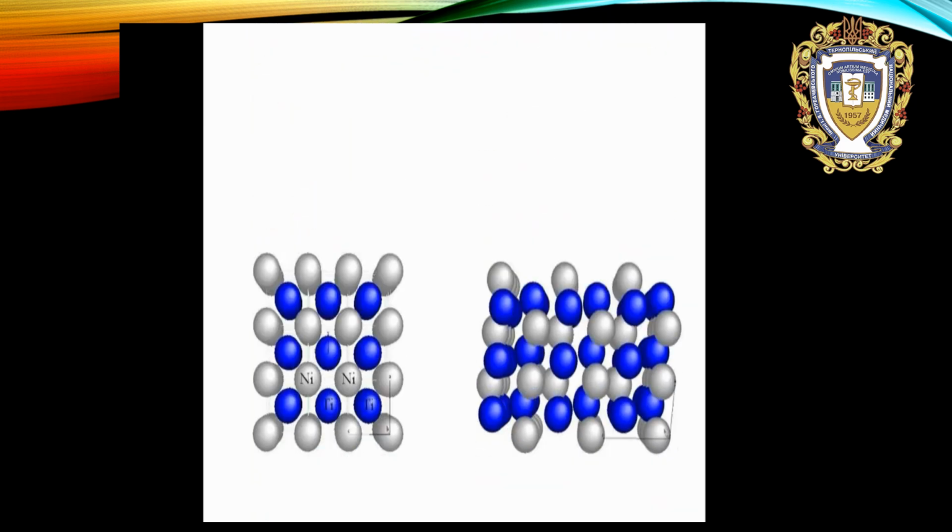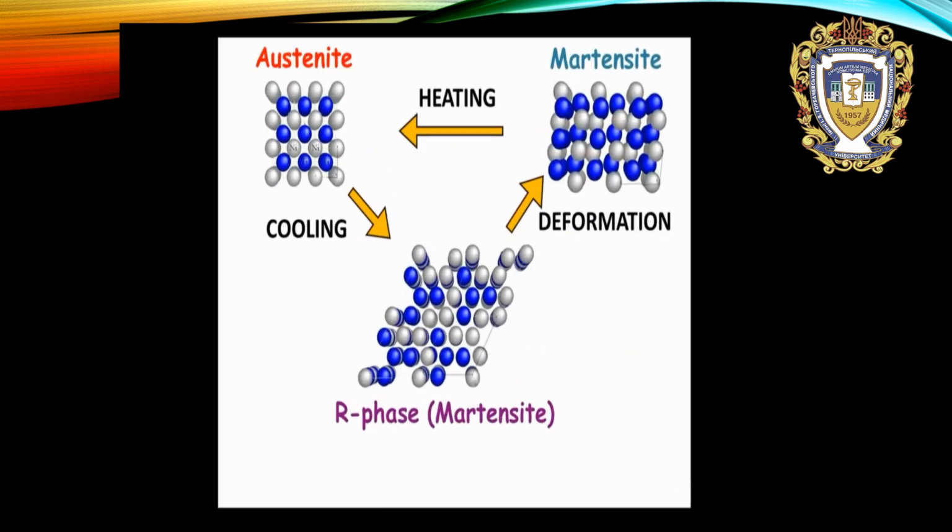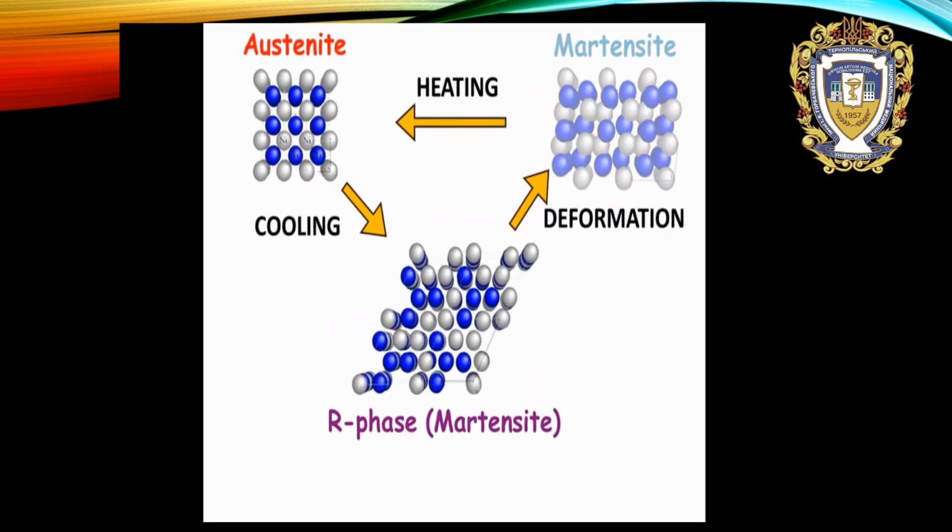In nitinol, the austenite phase transforms into the martensite phase, and the martensite phase then transforms back to the austenite phase. During the martensitic transformation, austenite distorts into martensite by moving atoms by less than one interatomic distance. Due to the diffusionless nature of the transformation, no change in composition occurs. The transformation process may include an intermediate phase called R phase as another martensite candidate. Such a transformation path is also known as two-step transformation.